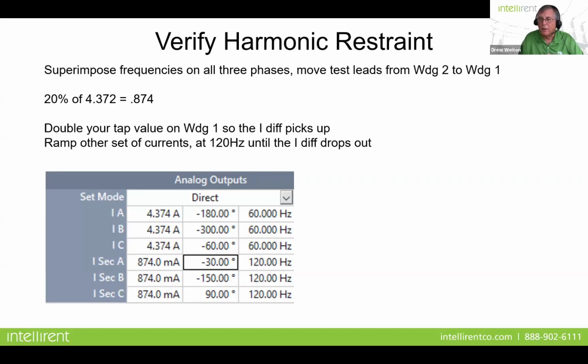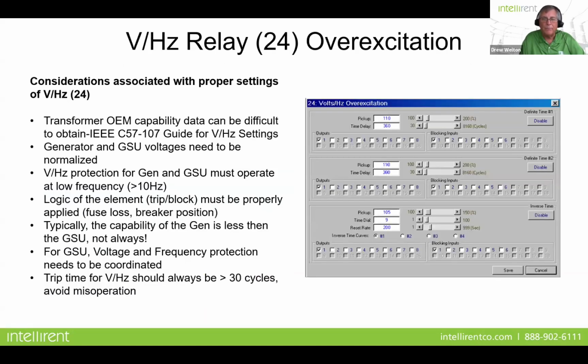Now, if you're going to do fourth harmonic restraint, we just double this, right? That's going to be 240 hertz. So this is a nice, tricky little way to check your harmonic restraint.